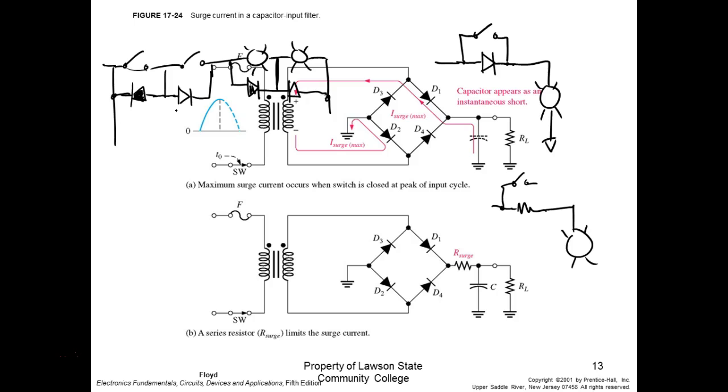So this is doing the same way. So this would be my AC. With the switch closed, we'd get full voltage across the light bulb, and it would burn real bright. We open the switch, then we get V peak over pi, right? And the light bulb would dim down. So this is a real cheap light dimmer. But you only had 2 stages you could go through. You had it wide open or half dim. That might be what you're talking about. And that's just a little circuit.